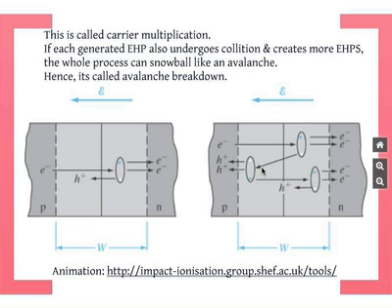But this hole now also has significant kinetic energy, so it can also undergo an impact ionization and transfer energy to an electron in the covalent bond, again pulling it out of the covalent bond. So it can create holes and electrons as well. Another electron goes this way, and this electron can also undergo impact ionization and create more electron-hole pairs. So you can see this multiplicative effect, an avalanche sort of process.